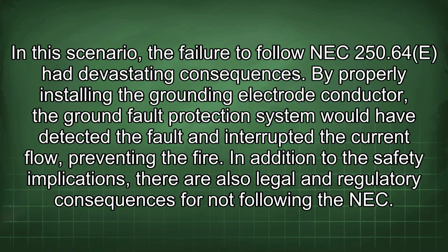In this scenario, the failure to follow NEC 250.64e had devastating consequences. By properly installing the grounding electrode conductor, the ground fault protection system would have detected the fault and interrupted the current flow, preventing the fire. In addition to the safety implications, there are also legal and regulatory consequences for not following the NEC.